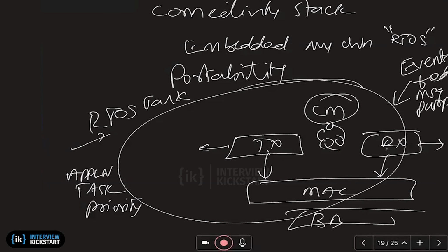And I was talking about porting to the bare metal. Right. So what I'm saying is this is designed for bare metal. Therefore, it can be embedded within any RTOS. Okay. So the external interface for the stack is just that the environment feeds the events to it and it will run. Right. So that's how I make my stack portable to unknown platforms.